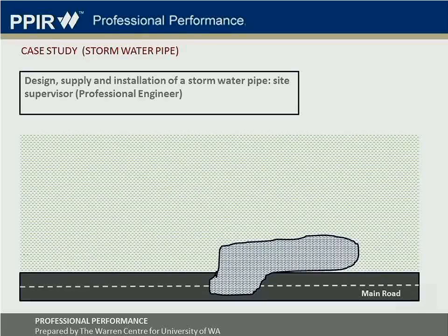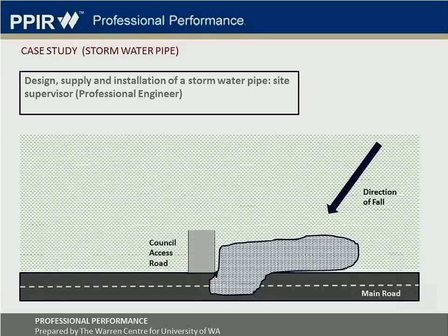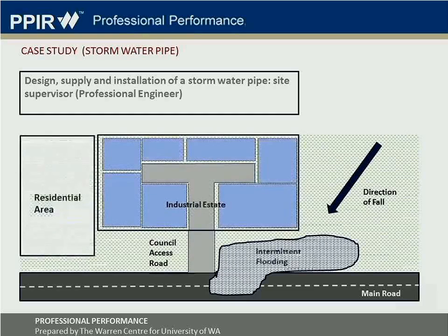With no drainage under the access road, which effectively acts as a dam wall, I better give you a bit more information here, I think. Flooding occurs during heavy rainfall. So this section, the shape that's very uneven, that's where the flooding occurs.